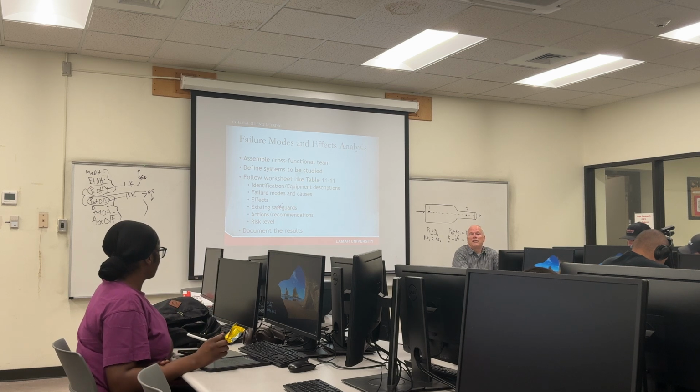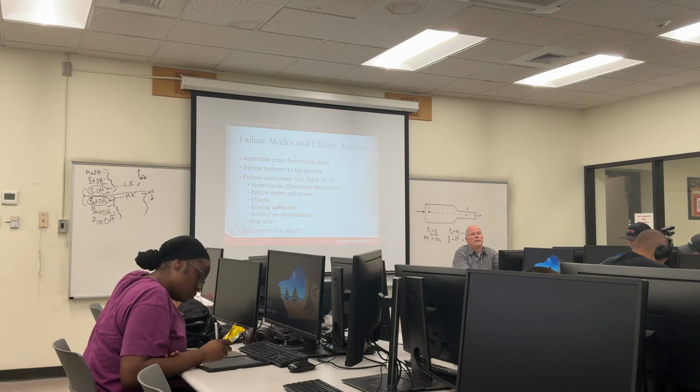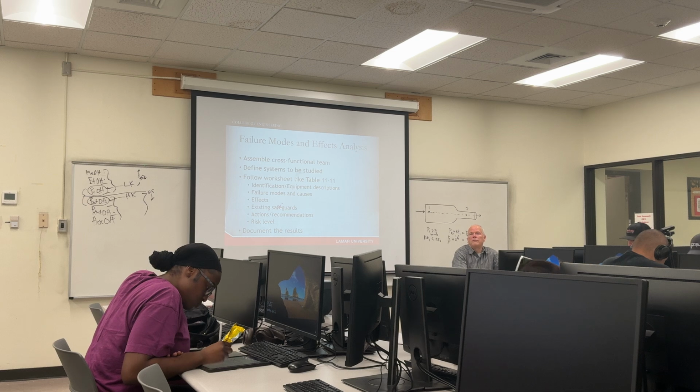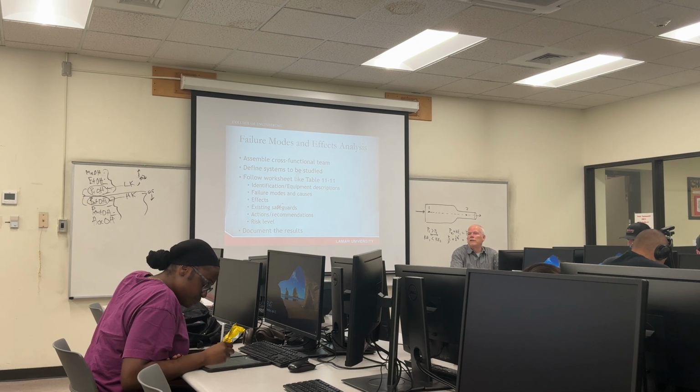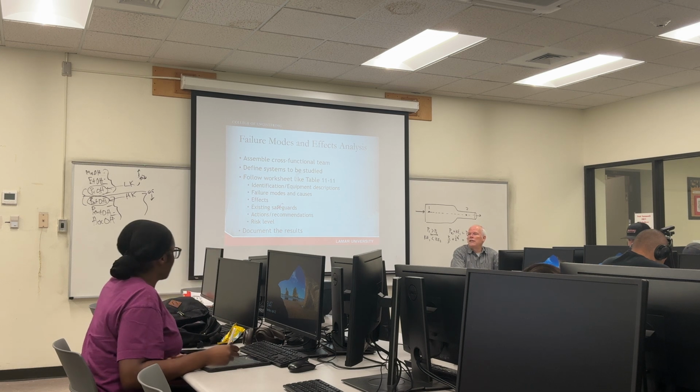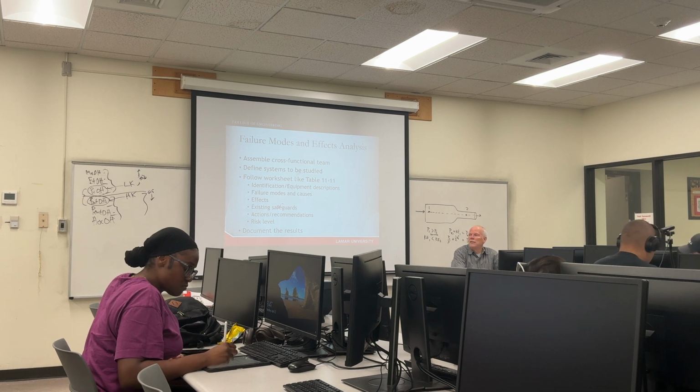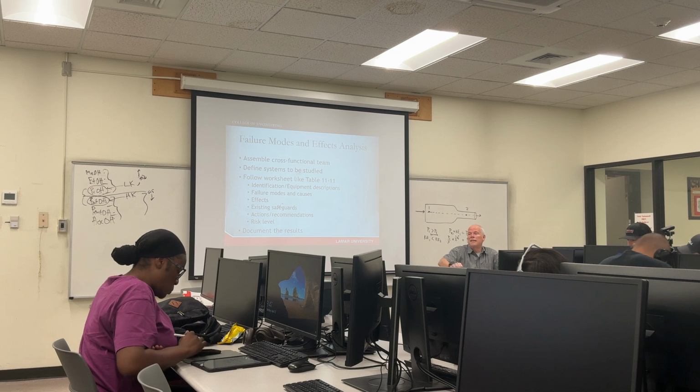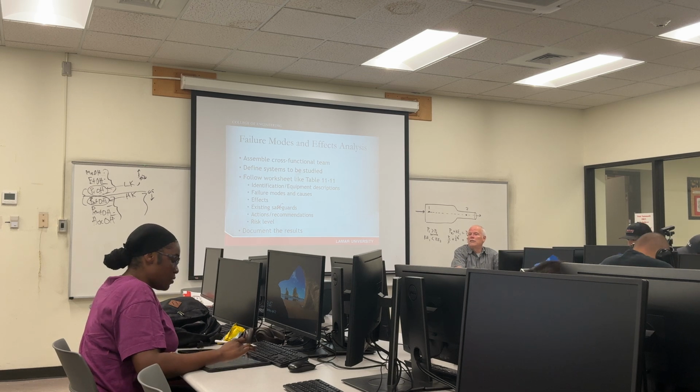We talked about scenarios before when we talked about relief valves. We said for each relief valve, you have to develop a scenario, because that's the only way you can figure out what size the relief valve needs to be. You have to have a scenario. This is something that happens, and therefore it causes this, and then I need to relieve this much flow. That's the only way you can size a relief valve, with scenarios.